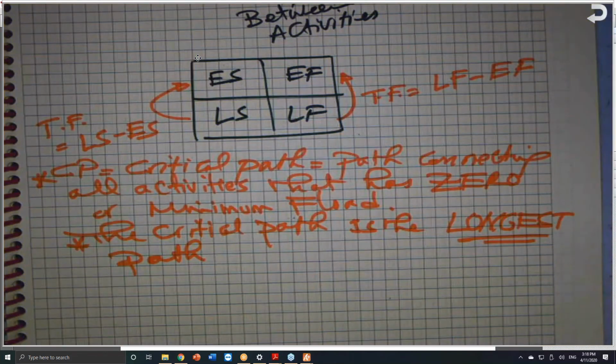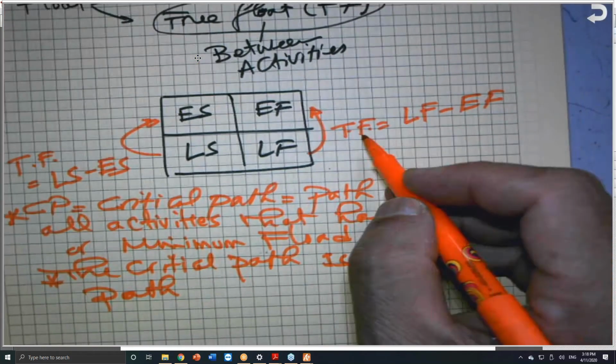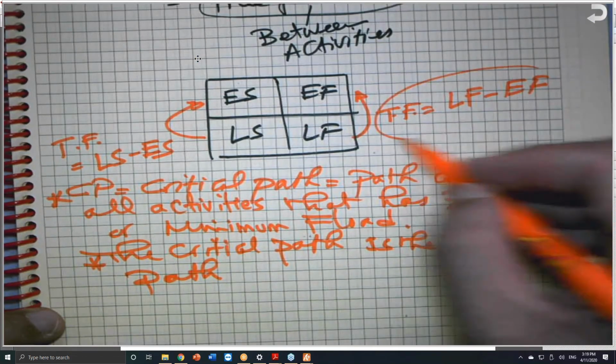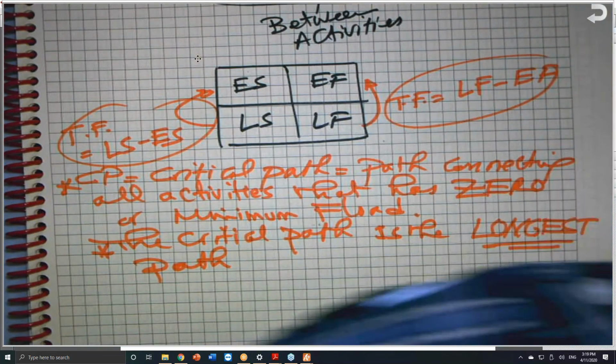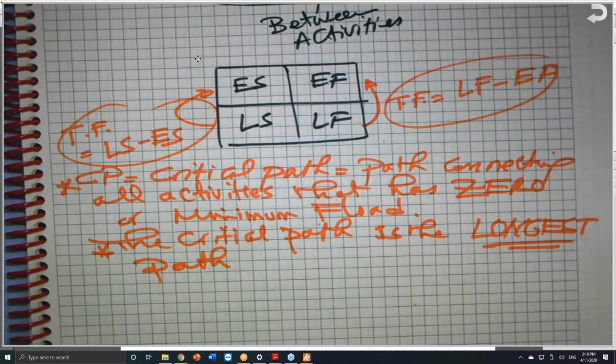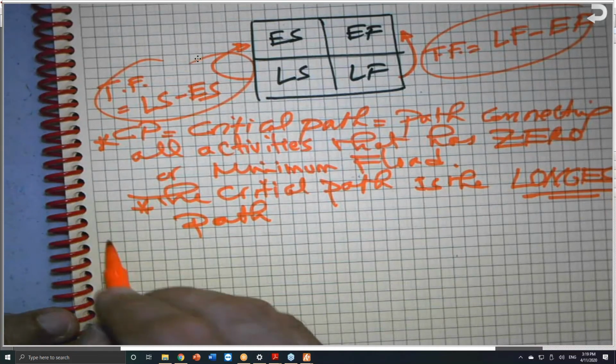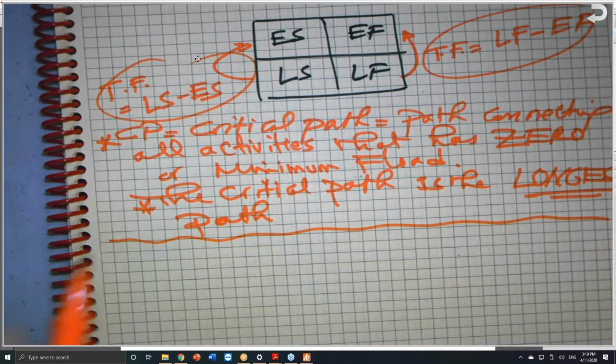The total float, the TF, is the amount of time that an activity can be delayed without affecting the delivery of the job. This is given also in all my books, and you know where it is, so at least to save time. I need you to be aware of this, and this is a very good problem.